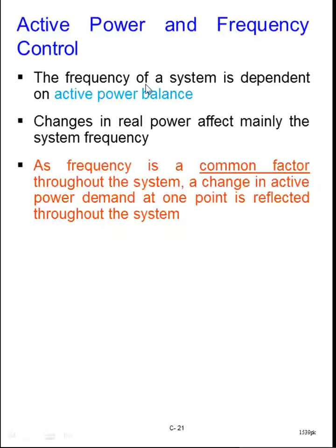So now, with those discussions, it is clear that active power regulation is reflected in terms of the frequency here, and thus the frequency signal will depend upon the active power balance in the system. Whenever you have a change in the real power, it will affect the system frequency.